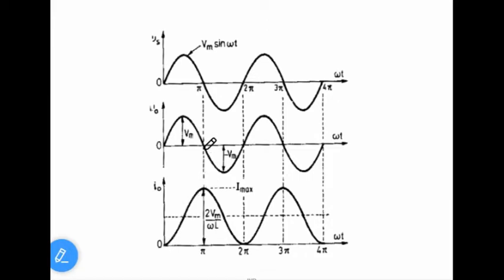If the voltage is 0, it means that the derivative should be 0, meaning current should be maximum. If the voltage is negative, it means that current is falling. Once again I will repeat, if the current is increasing with respect to time, voltage across the inductor is positive.